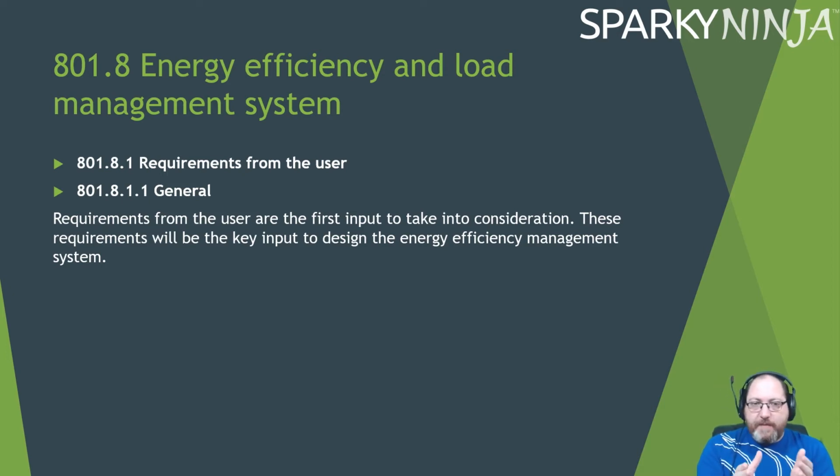It might be that a redesign needs to be considered on a scheduled EICR, for example, to consider if there are any changes that can be done to improve energy efficiency, either by introducing a mesh layout, changing the lighting, changing the switching, introducing power factor correction. Again, all stuff that we've probably done for the past 10 years or so now. Changing to LED lighting, for example, introducing sensor switching. It's all stuff we've been doing.